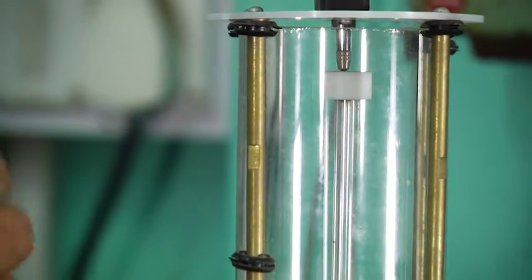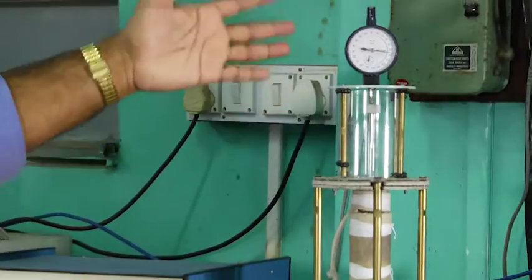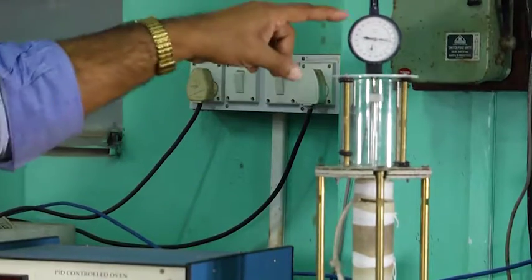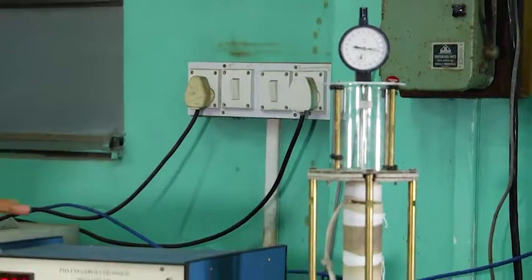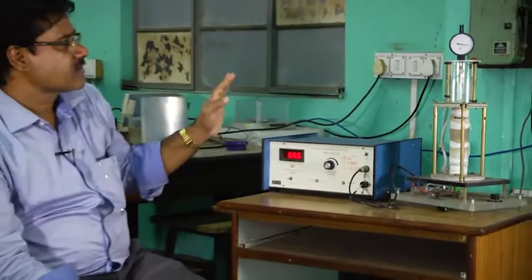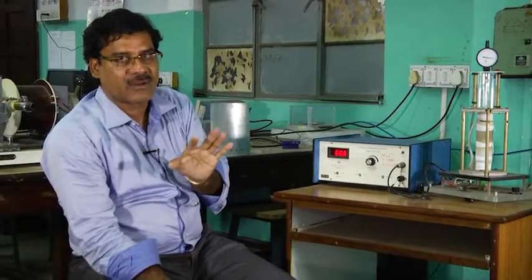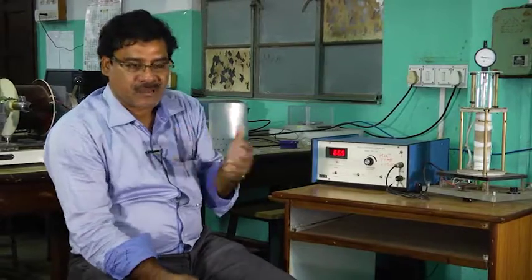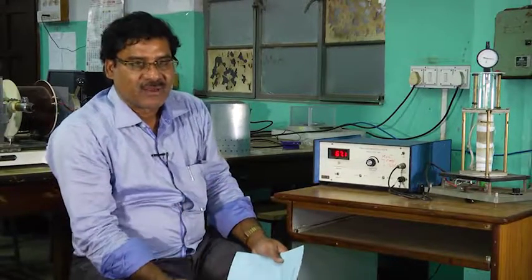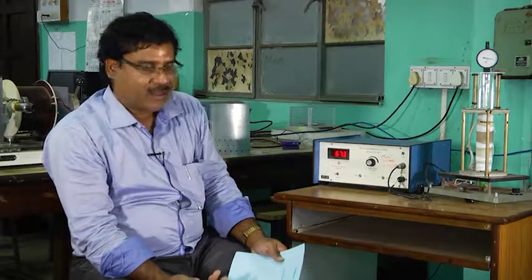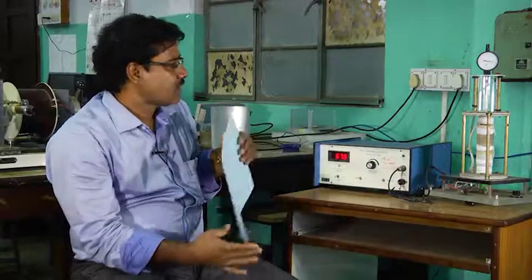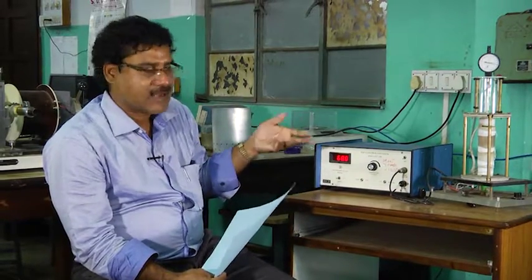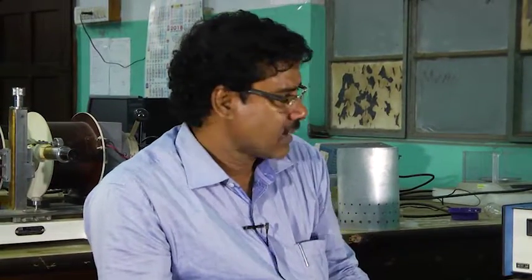So, why is it pushed? Because of the expansion of the rod. So, the expansion of the rod is directly related with this reading, and the temperature we are getting from the thermocouple. So, temperature versus this expansion, that data only we have to take, and as I told, from plotting the graph you can find out del L by del T, and you will get the linear expansion coefficient. So, I think in the next class I will discuss the data analysis and error calculation. So, I will stop here. Thank you.